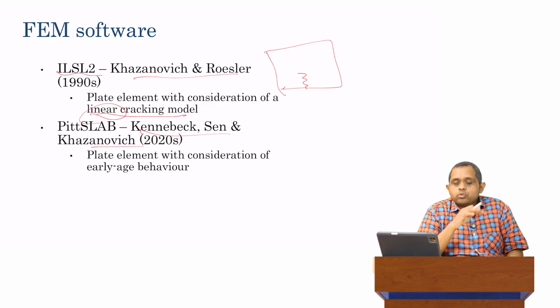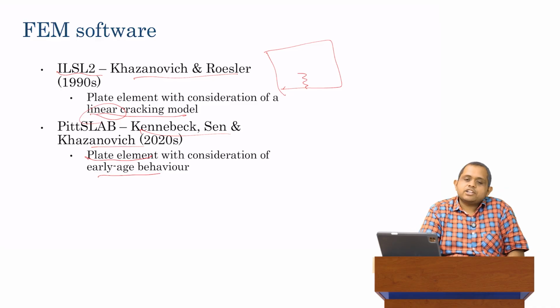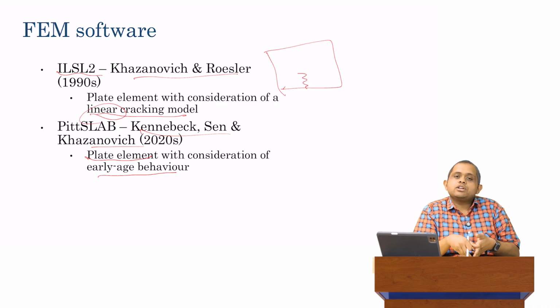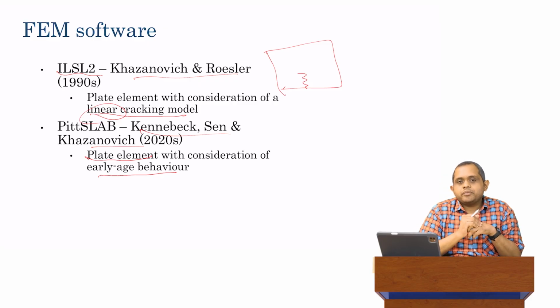This was still based on the ISLAB formulation, in the sense that we were still using plate elements, and the program also had consideration of temperature. One interesting addition was consideration of early age behavior. Early on, when you just pour the concrete, it is still setting and therefore very weak, and its modulus and strength are still being gained. So besides all the capabilities of ISLAB, it included consideration of early age behavior, which today is also considered a very important aspect in rigid pavement analysis.